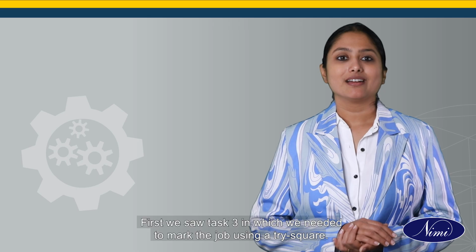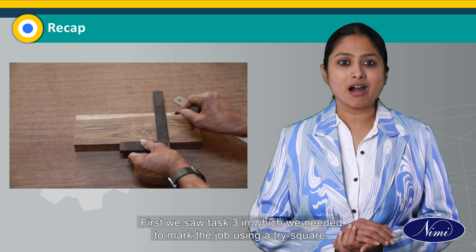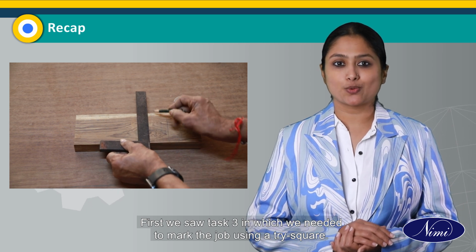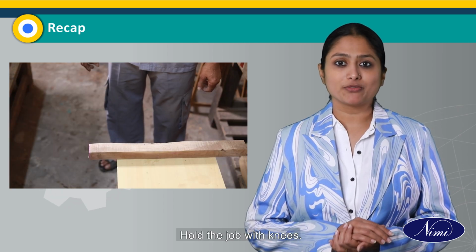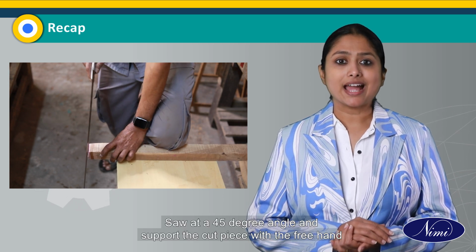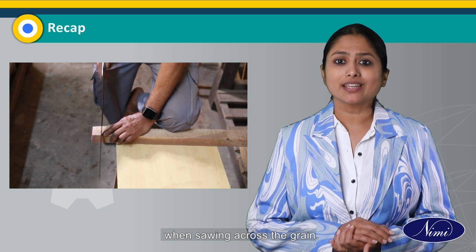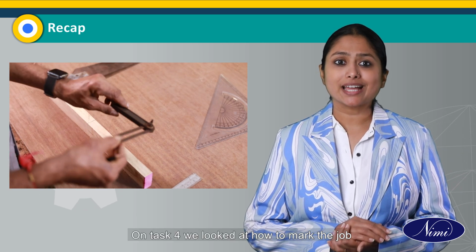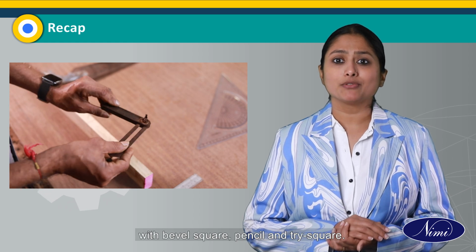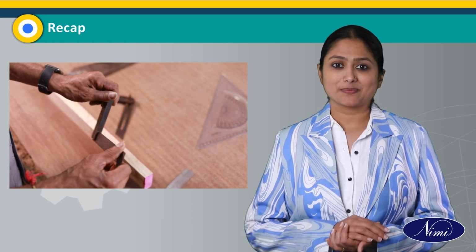Recap. First, we saw task 3 in which we needed to mark the job using a tri-square. Hold the job with knees. Saw at a 45-degree angle and support the cut piece with the free hand when sawing across the grain. In task 4, we looked at how to mark the job with bevel square, pencil and tri-square.